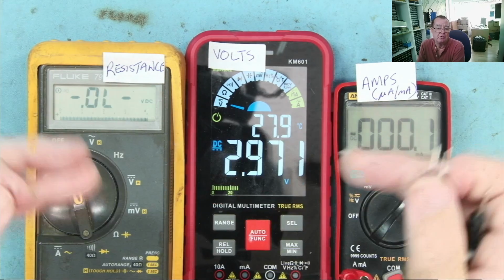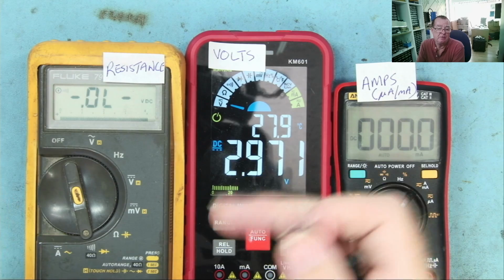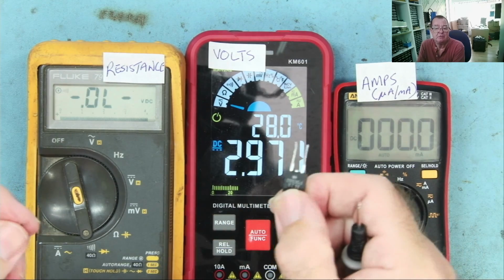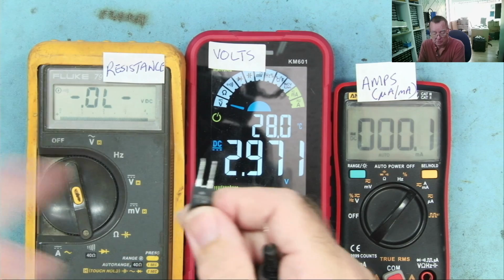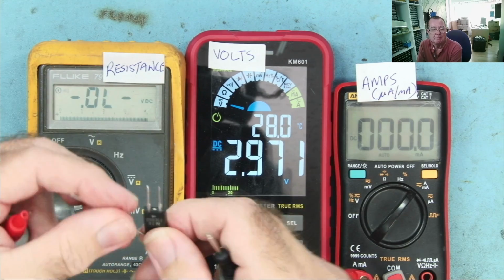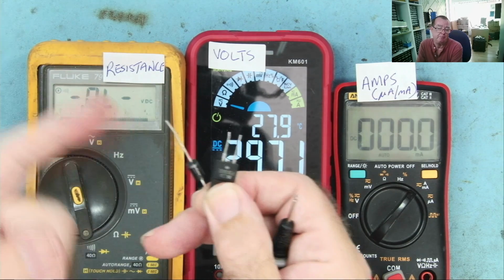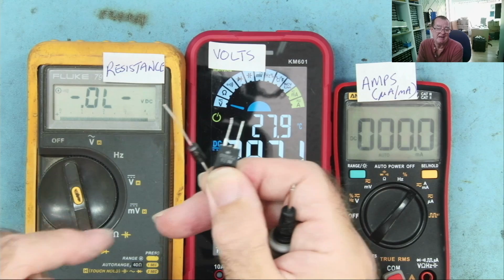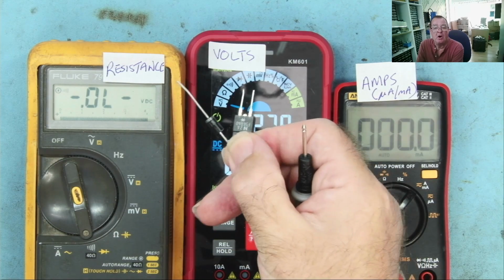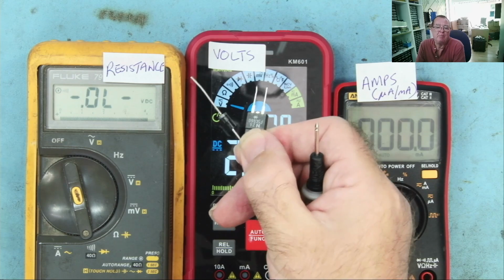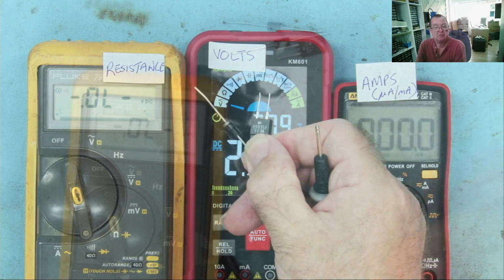One is a constant voltage source with too low a voltage to turn on a semiconductor junction. The other one can turn on a semiconductor junction, and because you need to limit the current flowing through that junction, otherwise you'll just burn it out, it is a constant current source. Okay, hope that was clear, because that will be useful to us in the next part.